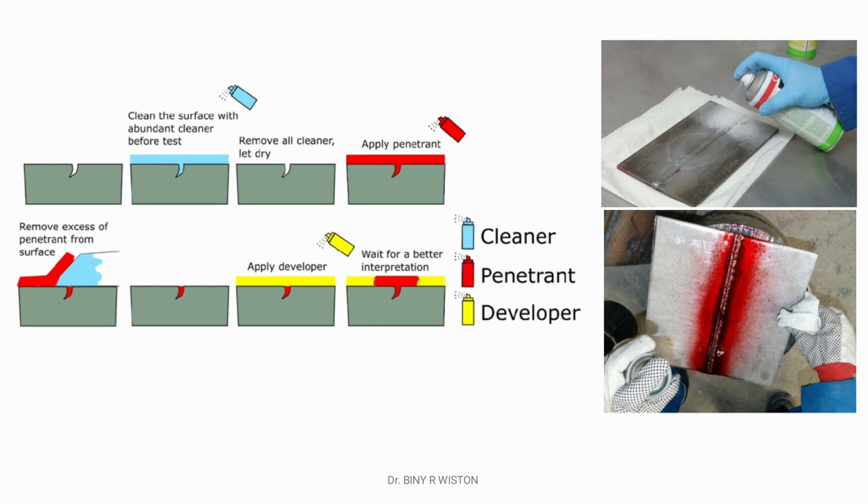The second step in the inspection process is the application of penetrant fluid to the cleaned surface. The fluid should spread freely and evenly over the surface and move into the cracks. The application of penetrant may be achieved by dipping the component in a bath of penetrant liquid or by spraying or brushing. A minimal dwell time of about 20 to 30 minutes may be allowed after penetrant application. A larger period may be necessary in certain circumstances.